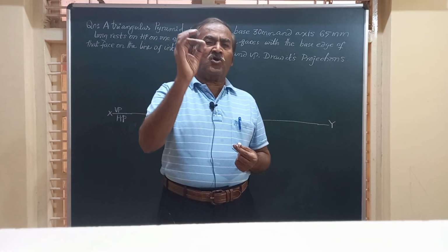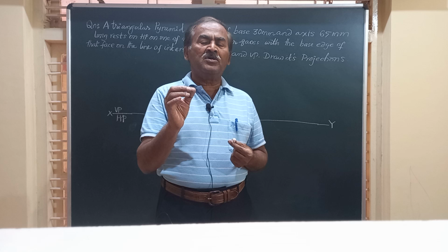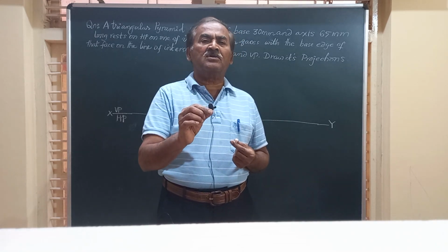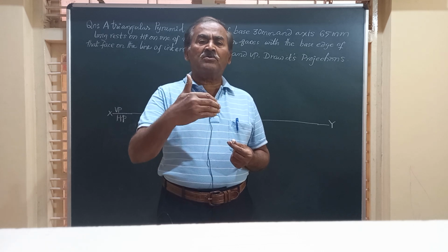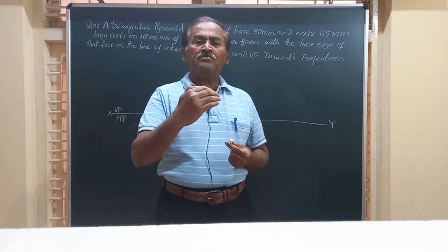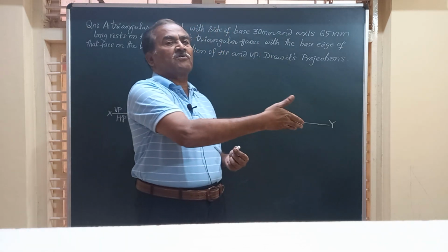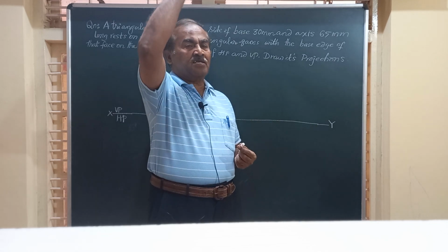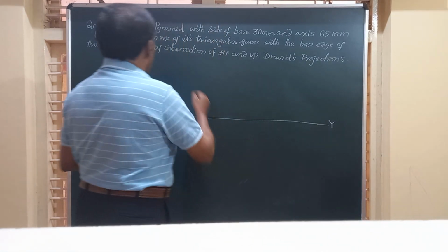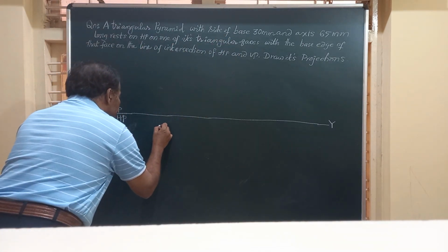Friends, for all the pyramids, whenever it is stated in the problem that it has to rest on one of its triangular faces, position the solid on HP such that one of the base edges of the solid is to the right side of the observer, and obtain the top and front views of the pyramid. Now, friends, I am going to construct a triangle of 30 millimeter side.